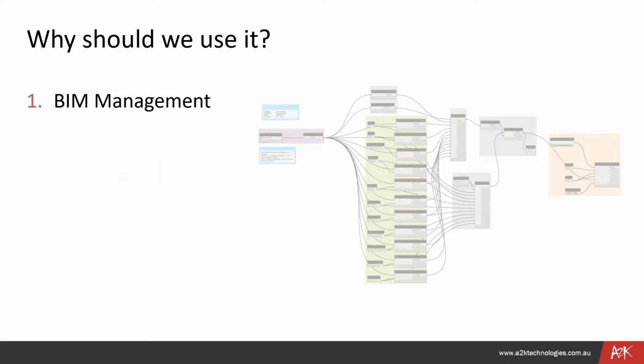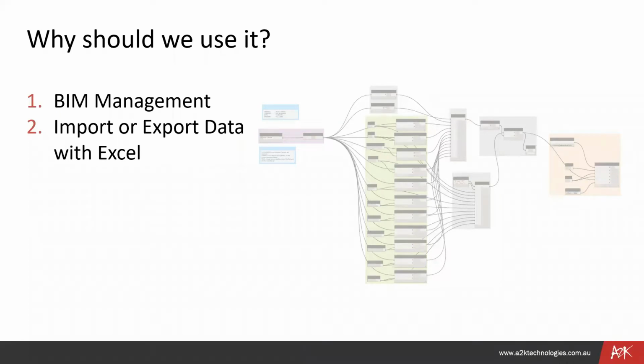Why should we use it? For a few things: BIM management, importing and exporting data with Excel. So that's where you really get into your parameters, instance type, and shared parameters, and you can manipulate them in Excel and push them back and forth between.